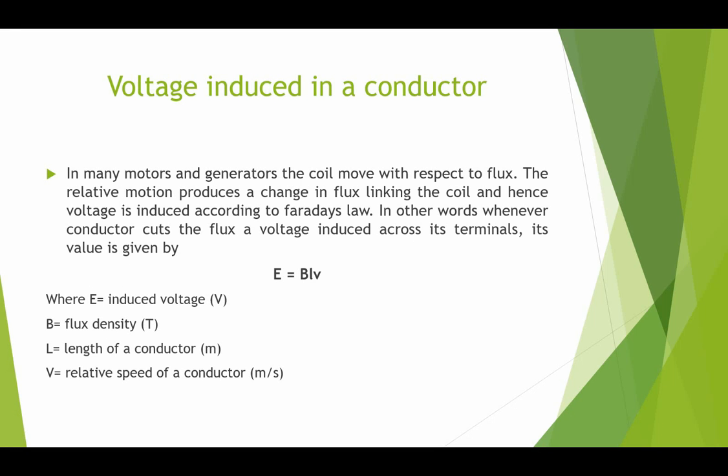Voltage induced in a conductor. We have studied that when the flux linked with a coil or conductor changes, an EMF or voltage is induced in the conductor. So how does it happen? In many motors and generators, the coil moves with respect to flux.